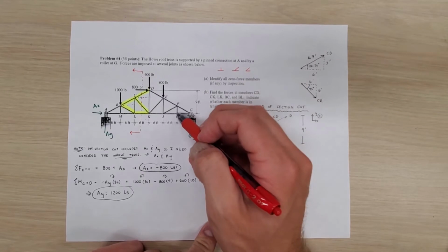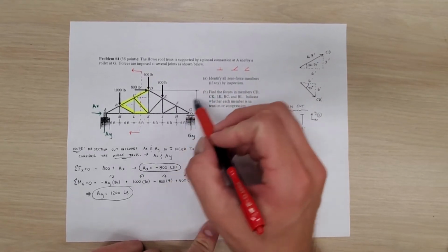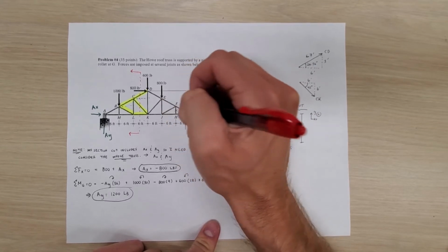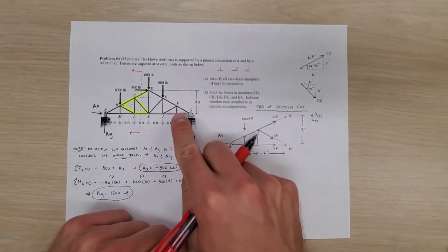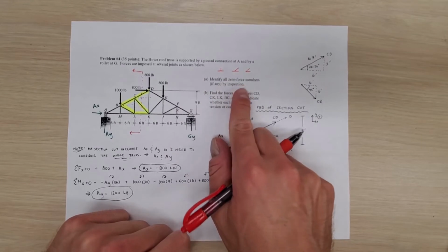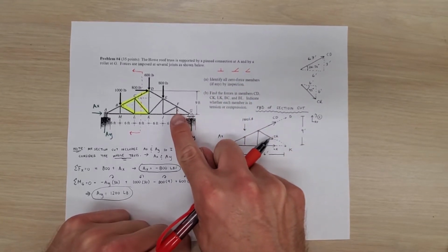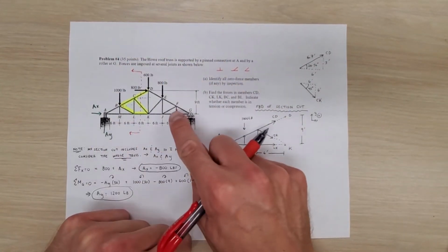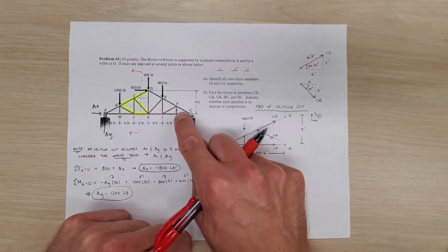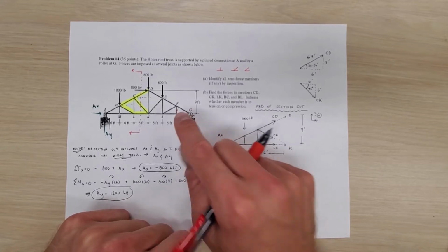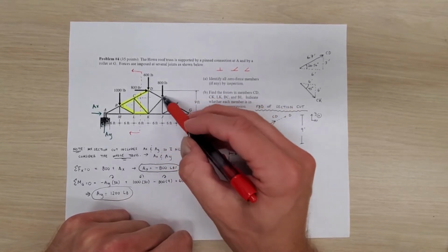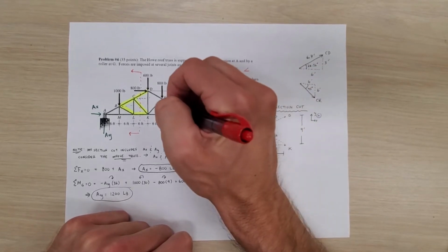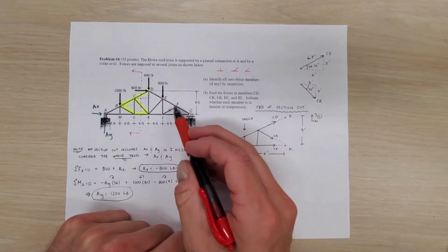So we can see right here at joint H, we've got a T. It looks just like this. So as a result, member FH is going to be a zero force member. Now what's important about zero force members is that if you identify this member as a zero force member, you have to remove it from the truss altogether and analyze the truss as if this member didn't exist at all. So if this member didn't exist, you would see now that JF would intersect EF and FJ in this methodology right here. So this would be a zero force member as well.